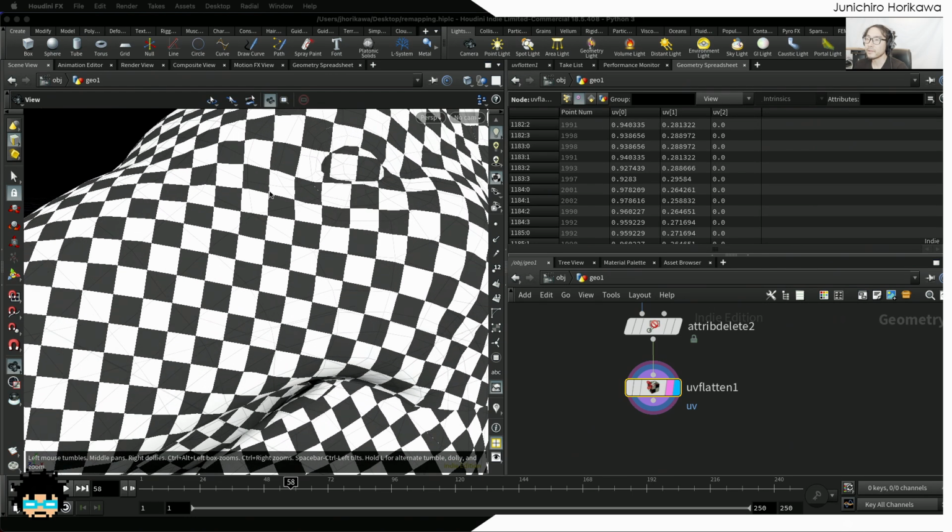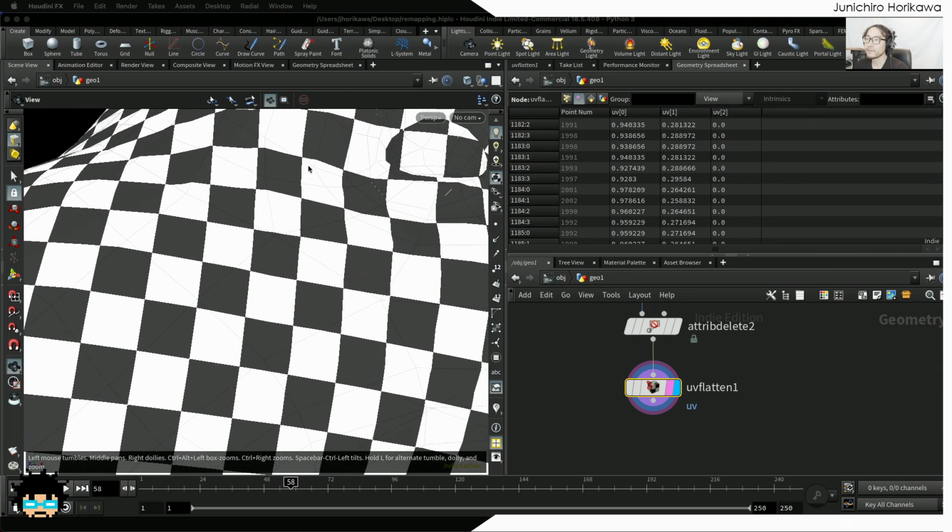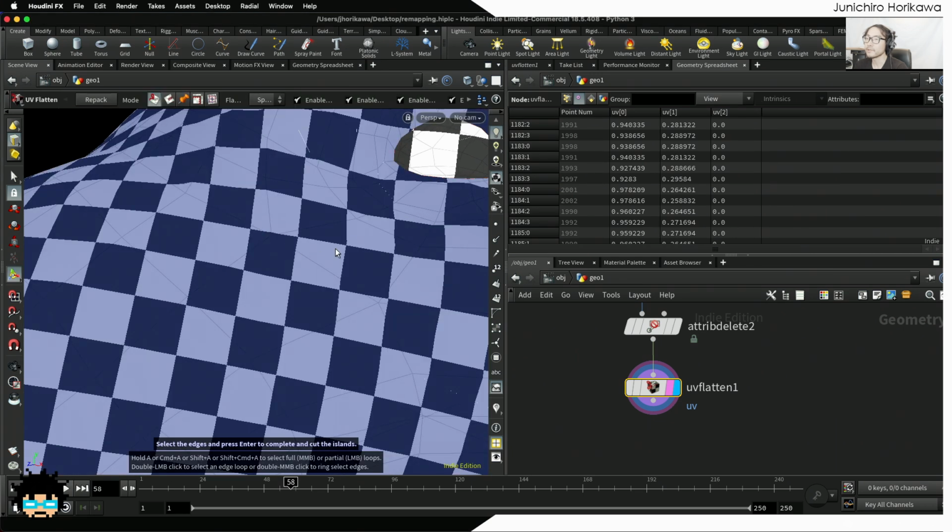Now currently the UV value is used to determine the texture positions, but I would like to use this UV as a direct point position of the surface, and maybe being able to change between the point position and the UV position using a Lerp might be interesting.